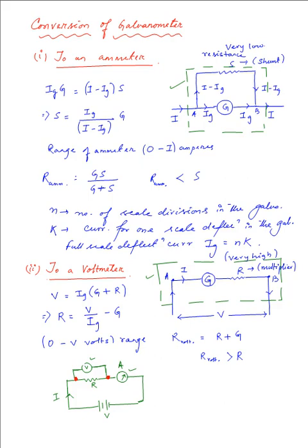The voltmeter is connected in parallel. Now what essentially happens is that the current cannot pass through the voltmeter. It will be completely negligible because the voltmeter provides a very high resistance to the flow of current in that path, and as a result a very feeble amount of current will flow through it, which is highly negligible because the multiplier resistance is maintained at a very high value.